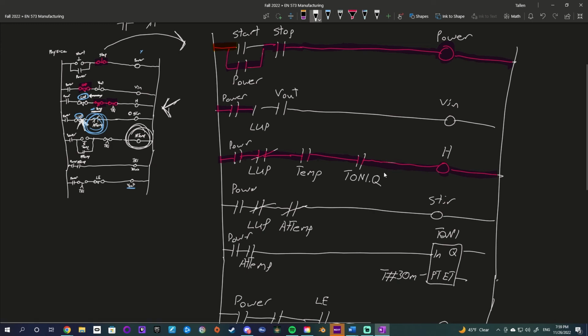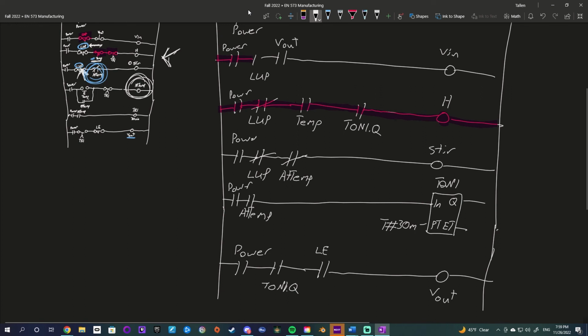As I mentioned before, the temperature is going to keep bouncing around as it hits temperature and goes above. If our temperature target is 100 degrees, it's going to hit 100 degrees and turn off, then hit 99 degrees and turn on, and just keep bouncing between those two, which is fine because we're trying to keep it at that temperature. I'm sure there are some really advanced control systems equations where you can maximize how effective that input and output is. I'm sure that's something we're going to be working on next semester. Whoa, can't wait.